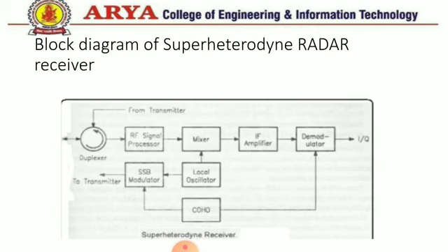Now in the receiver, in order to increase the signal to noise ratio and remove unwanted signals, the IF amplifier has characteristics similar to a matched filter. The matched filter performs the function of removing unwanted signal from the wanted signal.